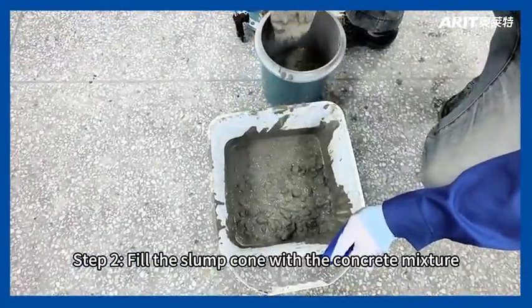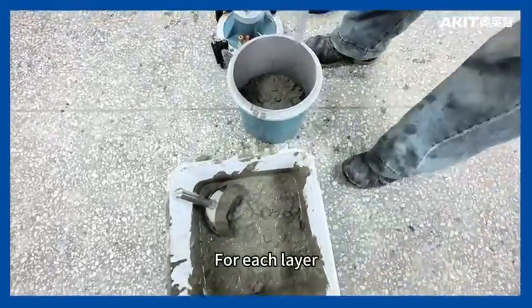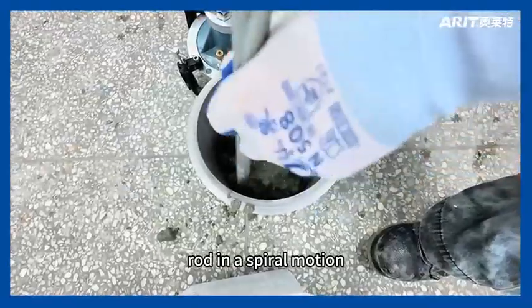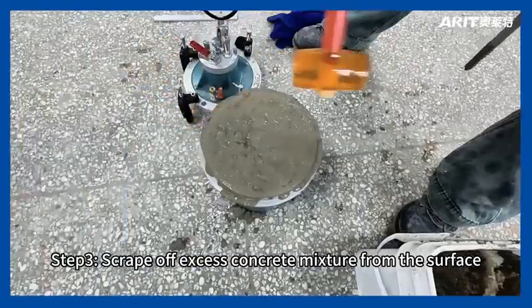Step 2. Fill the slump cone with the concrete mixture sample in 3 equal layers. For each layer, uniformly rod 25 times with the tamping rod in a spiral motion. After rodding, each layer should occupy roughly 1/3 of the cone's height. When rodding the bottom layer, the rod must penetrate the full depth. When rodding the second and top layers, the rod should penetrate through the current layer and just into the surface of the underlying layer.